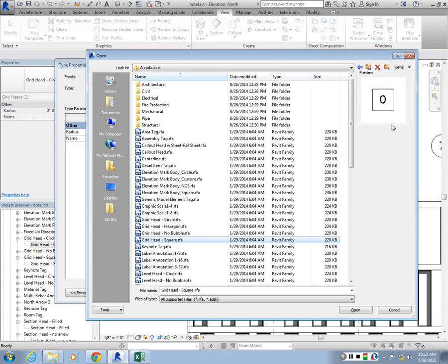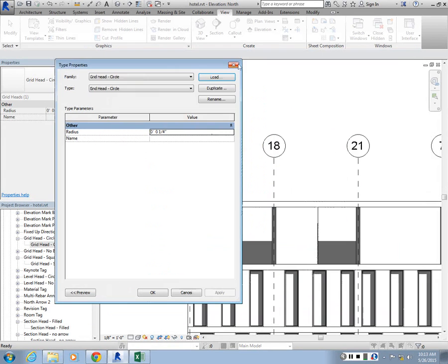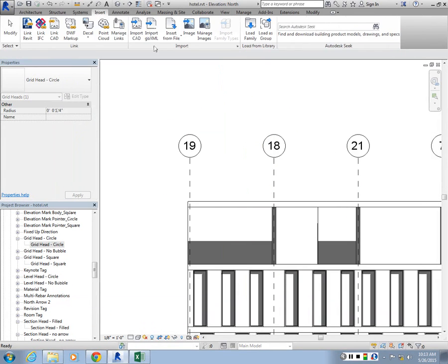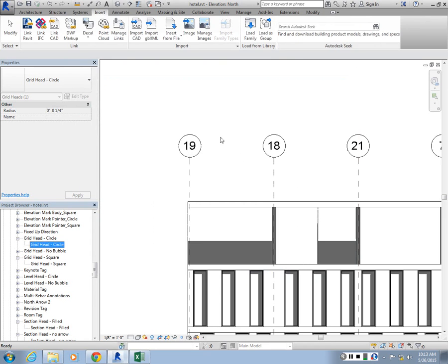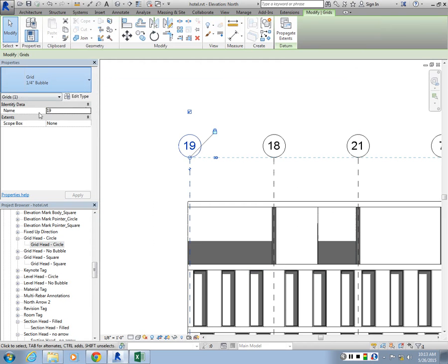Then you can override on that file as well. They will be updated, no? When you open the file, the link will be updated. You can go to the links, go to insert, manage links, and select the file here and right click and update or reload, something like that. But these you could keep them.